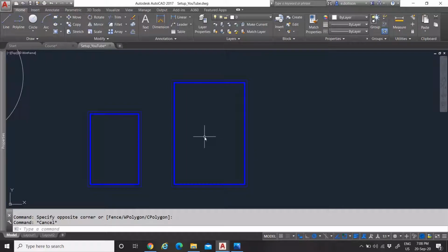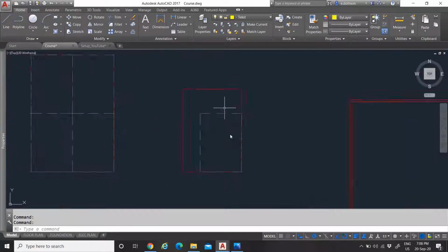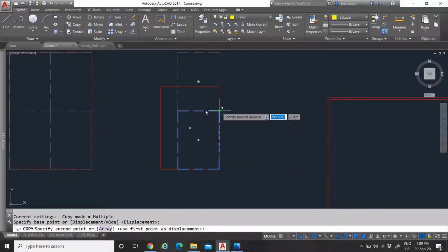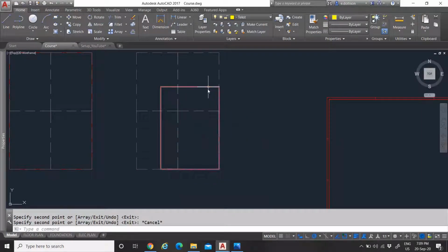Now, the A3 paper is actually a big size paper, so you would have to fold this paper. Normally we fold these papers, and here we can see an example of how it is folded. In the portrait size, it will be folded one like this vertically, and it will also be folded because this part overlaps the A4, so it will always show the A4 on the front, and here will be your title block.